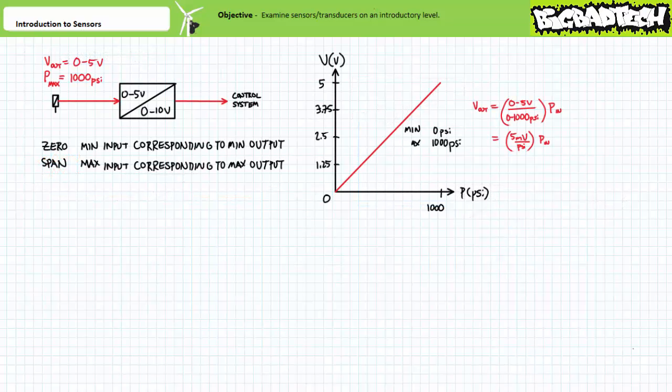Returning to the discussion of acceptable input and output ranges, realize the control system expecting a continuously variant 0 to 10 volt analog input signal largely does not care what this voltage signal represents. 0 to 10 volts could represent 0 to 100 psi, or just as easily 0 to 5000 psi. The continuously variant 0 to 10 volt analog input signal is a pilot voltage signal only.